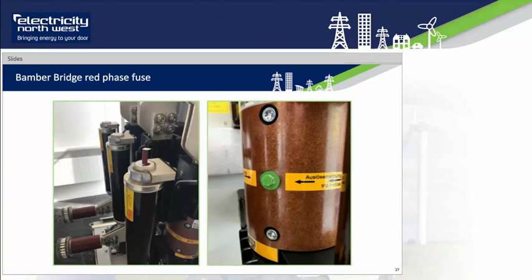When the main conductor has opened, the current still flows through the parallel fuse, where within half a millisecond the current is limited and finally interrupted, which is shown by the striker pin operated in the red phase on the left picture.